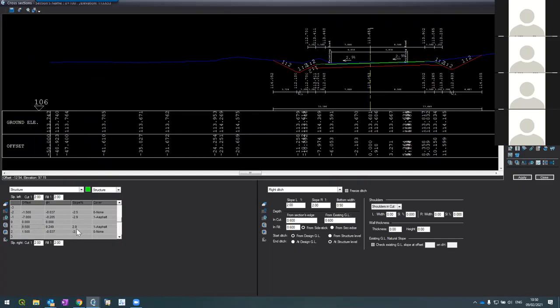Let me remind you that I changed the slope to minus 2.5, but in this case it's super elevated, so this is the reason. Then I stood here on the segment, right click with the mouse and send to all the sections from 100 to the last one that I wanted, 275. That's it. So this is how I change a specific segment and make it wider. I can do it for every section which I want. I hope you got this principle. Every section is an individual entity. You can change it, but you can use a template and do whatever.